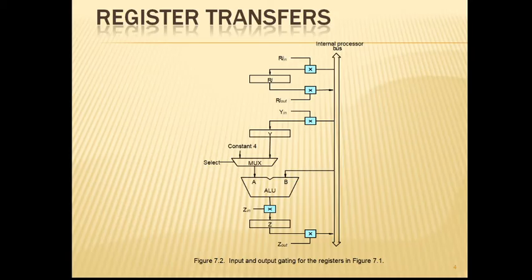Let us take one more example. For example, data transfers may use both the rising and falling edges of the clock. Also, when edge triggered flip flops are not used, two or more clock signals may be needed to guarantee a proper transfer of data. This is known as multi-phase clocking, because two or more clock signals will be needed for the proper transfer of data.